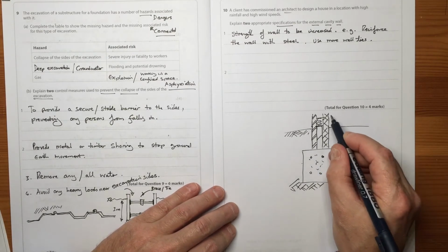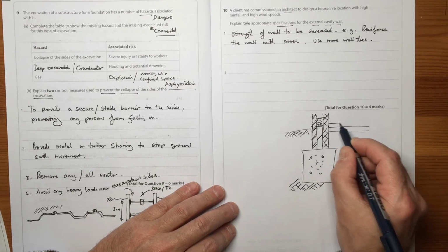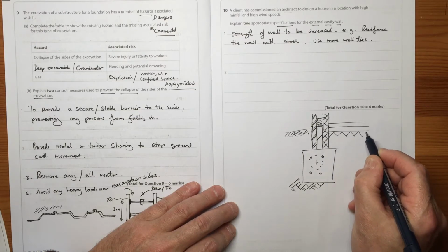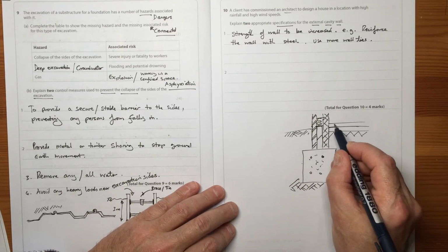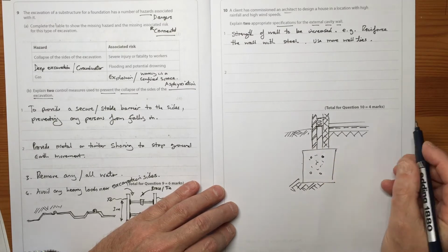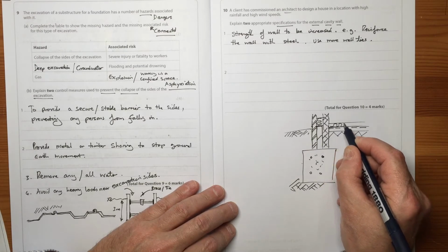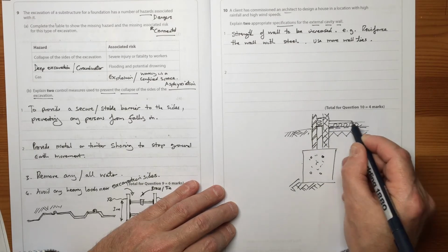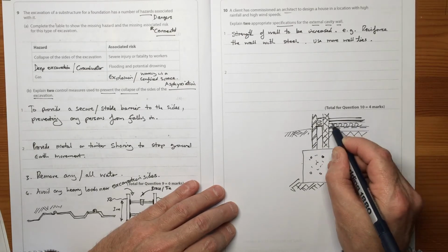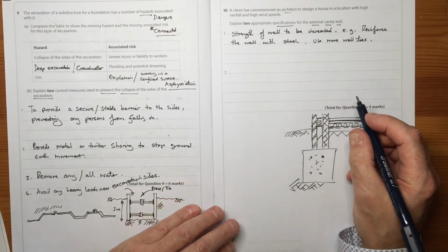And obviously it depends on the floor you're having, but you could have a mass concrete floor. Lots of insulation. All depends on the type of floor, so membrane. Insulation you could have on there. Another layer of concrete over the top, and a screed. All depends on the design for the floor. You'd have to be told that.